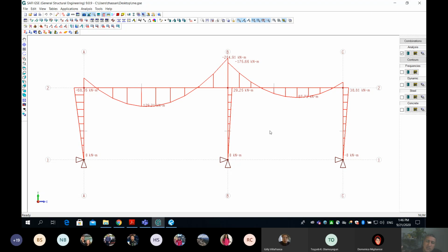So let me ask you, just go section by section, and you will see what I mean. Look at this joint here, okay? Now, what do you think? Do you think this bending is correct, this side is correct, given that it's on the tension side, or no, that's not correct? What do you think? That is correct, based on the column, because first of all, the support in the column is a pin, so there is no moment at that support, so the moment is on the top.